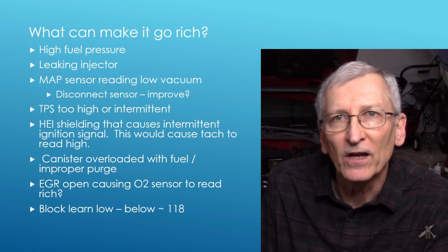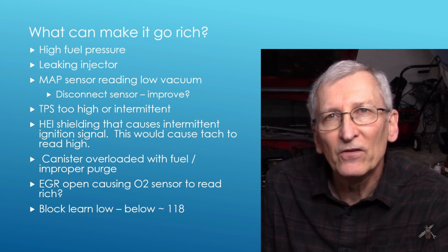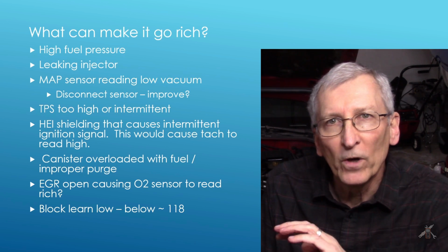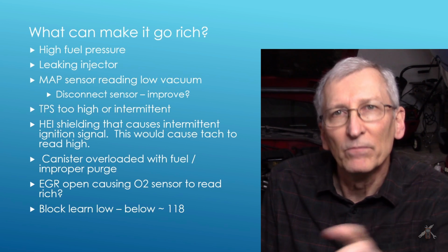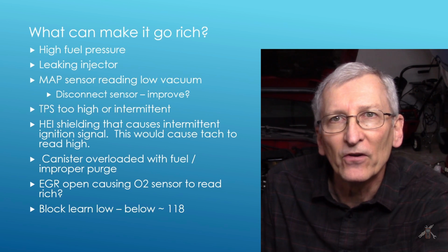In the meantime, the other way is go pull your spark plugs out and see, if you got a V8 and you got 8 plugs, and one is sooty and the other 7 are great, well, you got a problem on one cylinder and you might have a leaking injector on that cylinder.